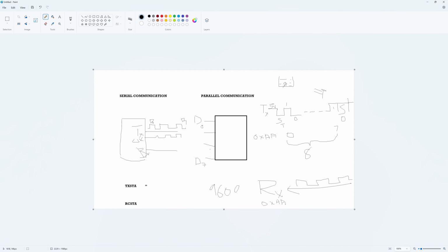If the guy on the lorry throws at a faster rate than the catching speed, the watermelon will get spoiled, it will fall down. So both need to be in good understanding of the throwing speed. Similarly here, both are in an understanding about the communication speed. This TX pin is transmitting at 9600 and this RX has to sample at 9600.